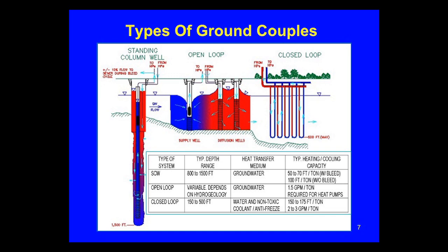If I put in a building with 250-ton capacity, which is a nice sized building, maybe, I don't know the size of this building, but let's say it's something like a building this size, it would mean I need 100 boreholes somewhere out there in the environment and tied into this building, okay? When people put in homes, they're putting in maybe 3 of those type of holes or 2 of those holes.